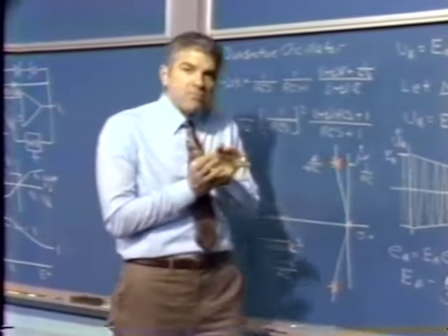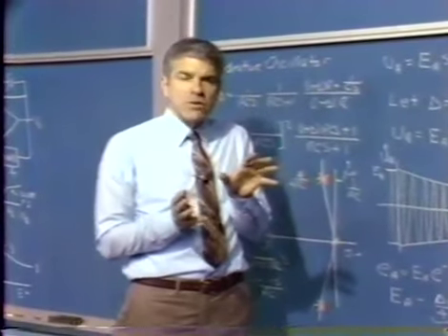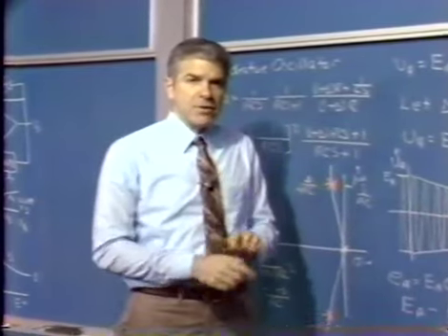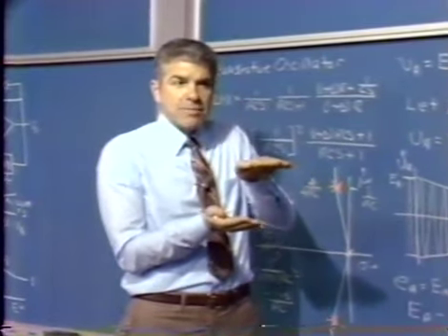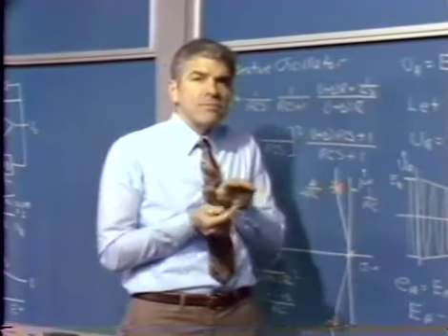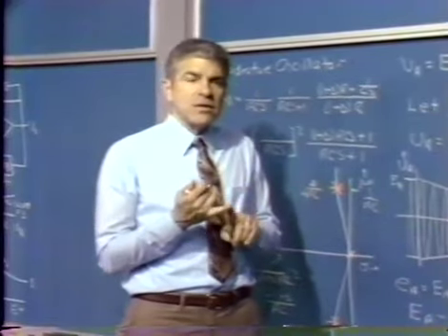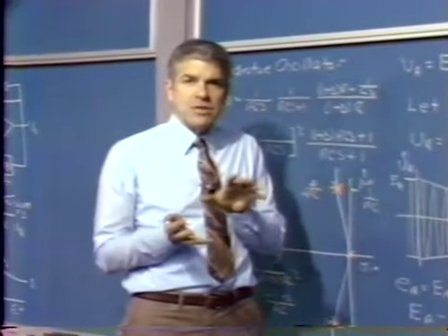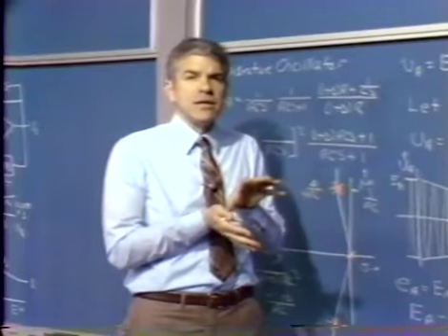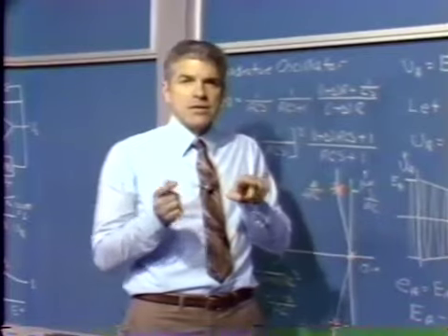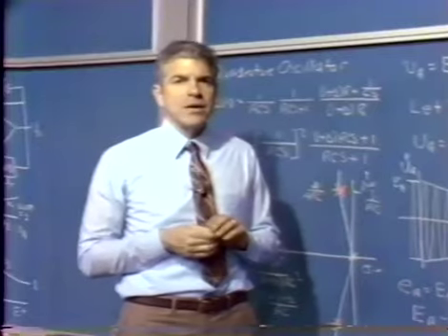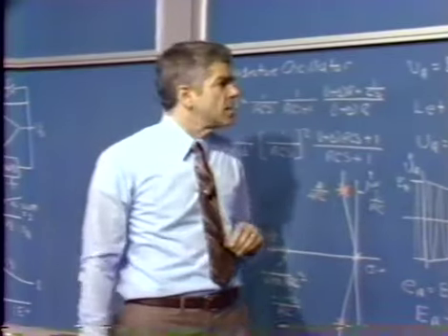The other one is a much, much slower loop, a much lower crossover frequency, that works on the amplitude of the signal, on the envelope of the signal, to keep that envelope constant in amplitude. So what we have to do is figure out a way to model the transfer function that goes from changes in delta to changes in amplitude. Our feedback system is going to measure amplitude, feed back to control delta, and clearly part of that loop is the delta to envelope or amplitude transfer function. We have to find out how we model that or how we represent that.